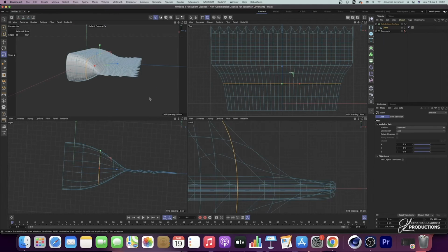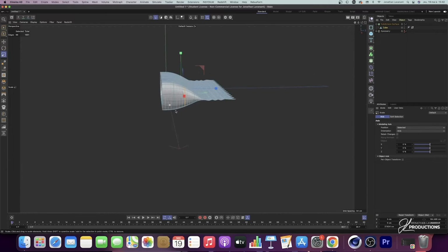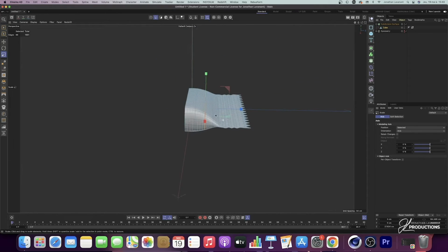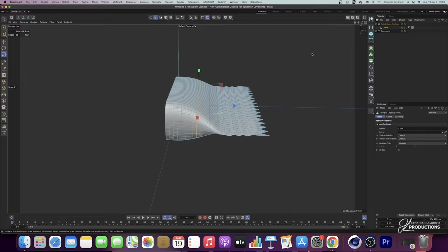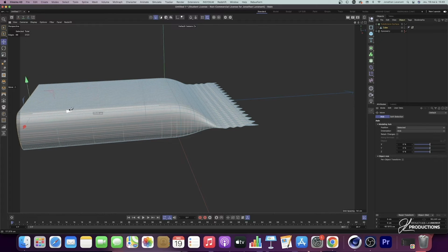So once we've done that, we're going to select our cube right here. We will be able to select the last loop at this level. We are going to do a left click with Control to add a large thickness like this. We will be able to put ourselves in top view here.